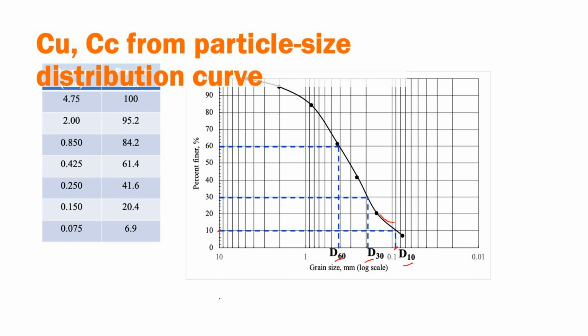So if we have some particular soil and we have a doubt whether the soil will perform better for a filter design or not, how do we find out? From the guideline we will know what this value could be. We'll find the ratio and we will see. I told you the soil should be permeable for the water, but it should not be permeable for the soil particles themselves to be taken away.